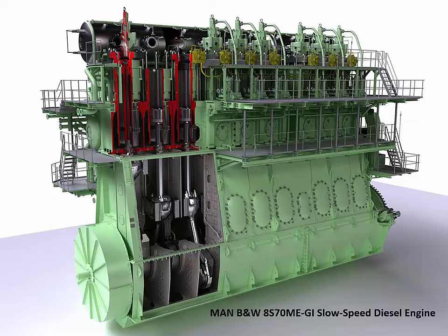But I also want to point out that this 12 consecutive starts is based on not having a lot of way on the vessel. Let's say you're coming into a port and you're doing the pre-test of the emergency systems prior to coming in. One of the requirements there is that you stop and reverse the main engine prior to taking arrival.